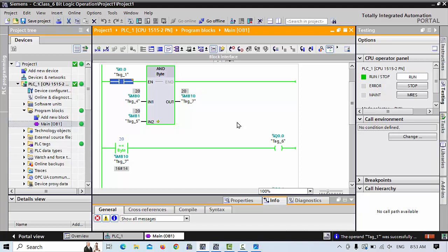And when you give the voltages from the source inside the PLC, for example, there is a proportional valve running at cylinders Y1 and Y2. If one has 10 volts and the other has 11 volts, it will not run, because the sequence and size will come out different. This is a safety for the cylinders, and you can also use it for accuracy. When this cylinder has 10 volts and this cylinder has 10 volts, they will move, otherwise don't move. Likewise when two motors are running, or conveyors are running with boxes on the upside, when they are equal, run. If not equal, don't run.